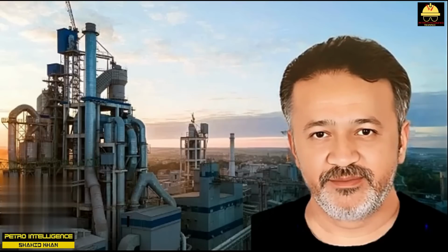Fin tubes. You may have seen bundles constructed with serrated, or very small, fins covering the exterior of the tubes. These are called low-fin tube bundles. These fins increase the outside surface area of the tubes by a factor of 2.5. However, this does not mean that the heat transfer efficiency of the exchanger will increase by 250%. Two factors curtail this improvement.